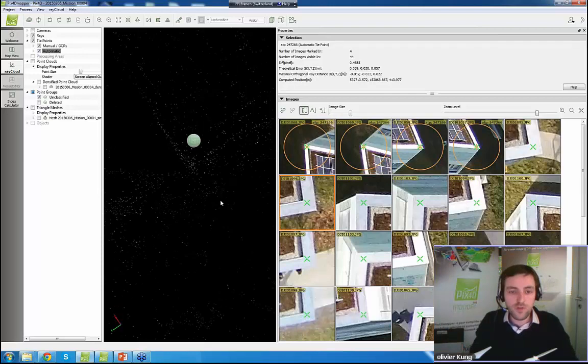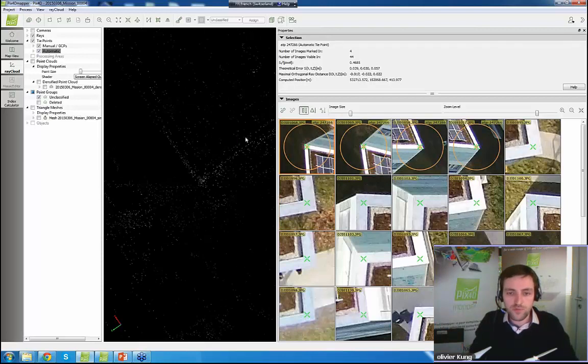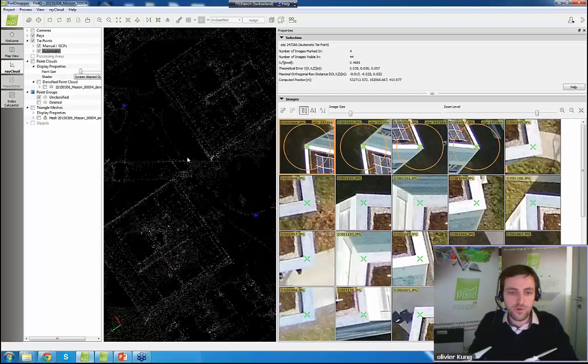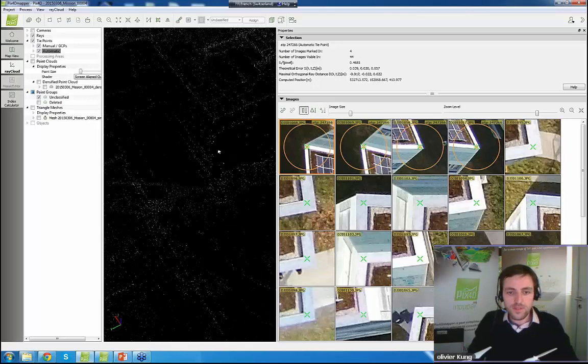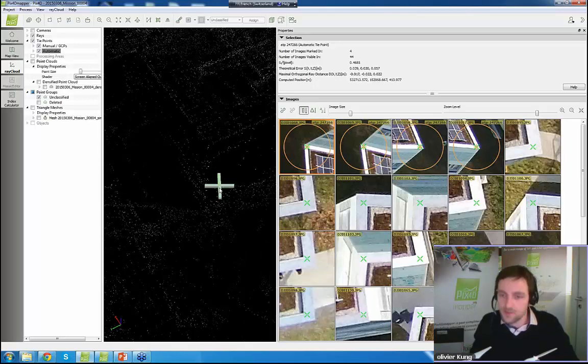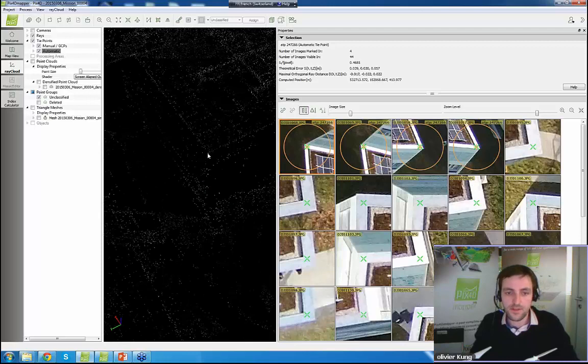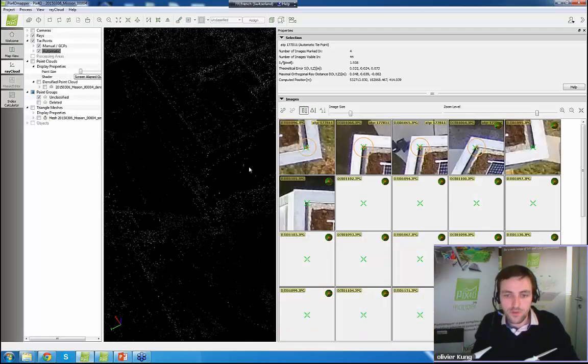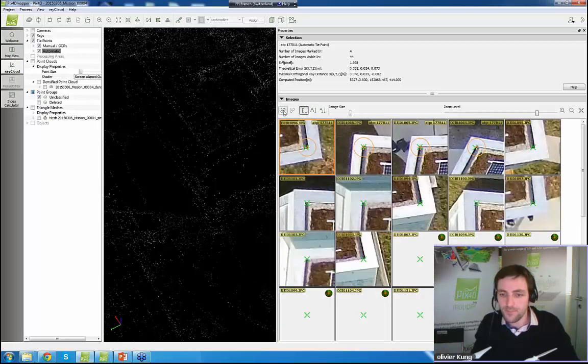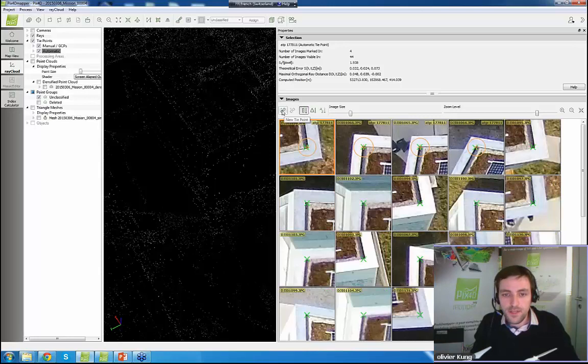So I'm going to quickly show this. To get a better 3D model, you have to display the automatic tie points, which are here. You select a place where you think the quality is not sufficient, or where something went a bit wrong. You click on a point that should be easy to detect, and then you click on that little icon there, which is called New Tie Point.